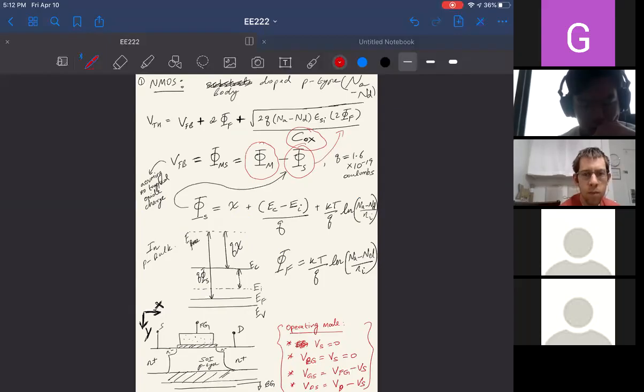So this is like a reverse design, okay? You know what the threshold voltage is. You need to choose the parameters, by choosing different materials, different dimensions of transistors and so on, to get that threshold using these formulas, okay? This is a good starting point that tells you how to choose the basic design properties of your transistor. Then you fabricate it, test it, and make some adjustments to make sure you get the correct values. That's an overall view of how these equations are going to be used in this project.